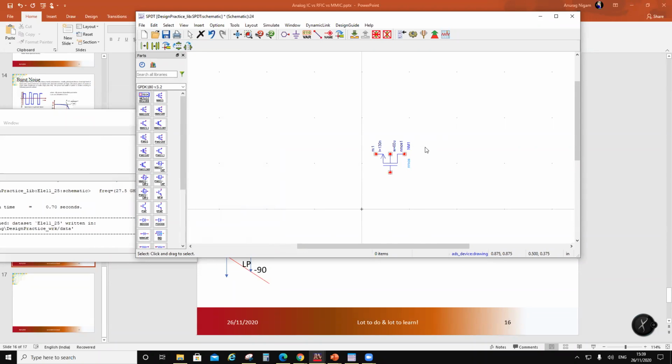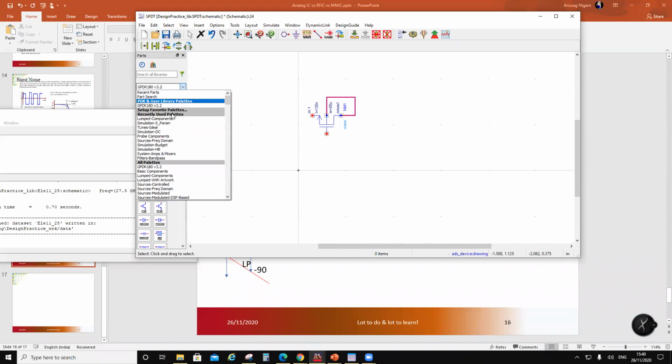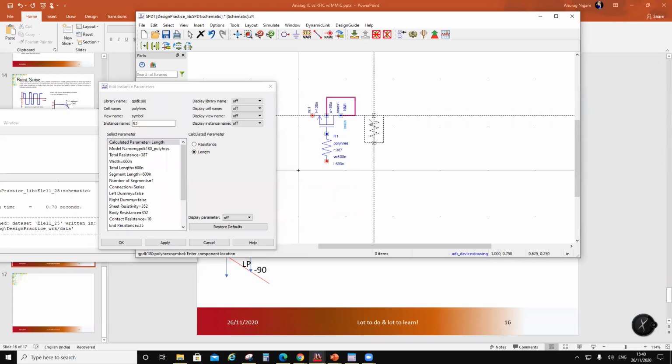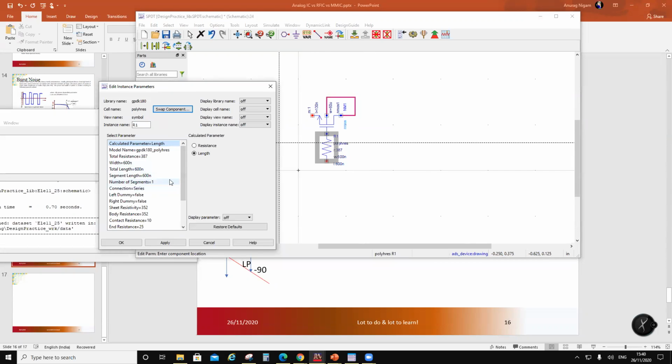Okay. So let's construct two paths. This is a series element. And then you are going to control the series element with some kind of a control signal. So here I'm going to put a big resistor, high res poly, and let's say this is 2K or something. If there is no current, then width doesn't matter. So this is a 2K element.